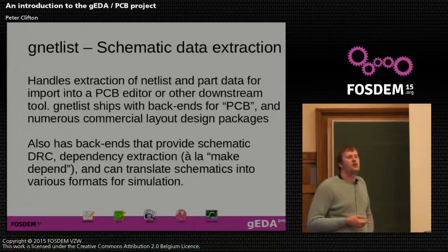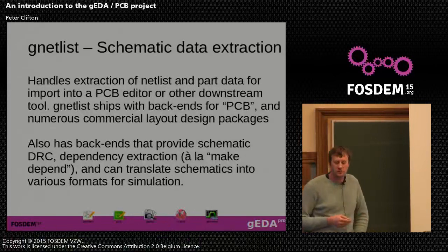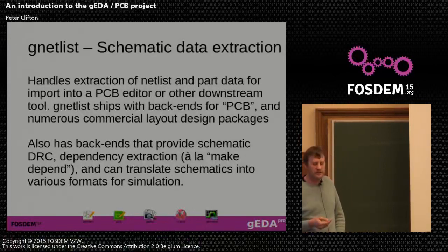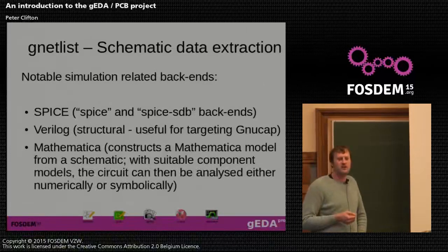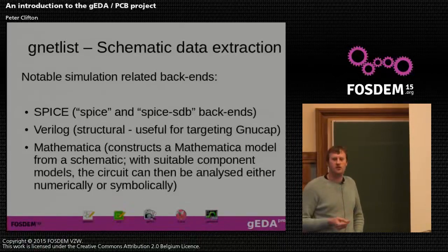Simulation targets, I mentioned before, I personally use gEDA as a front end for simulation more often than not. There are backends which try and elaborate the schematic in a way that can be fed to SPICE. Now, a lot of people were in the SPICE talks and the simulation talks earlier, which touched upon the fact that SPICE syntax is a little bit obscure and has certain requirements, like a resistor needs to begin with the letter R and a capacitor needs to begin with the letter C. So the SPICE backend does a little bit of mapping behind the scenes to make sure your component names try and match legal SPICE syntax, and you might have a fighting chance of getting a netlist out that will simulate without too much hand editing.